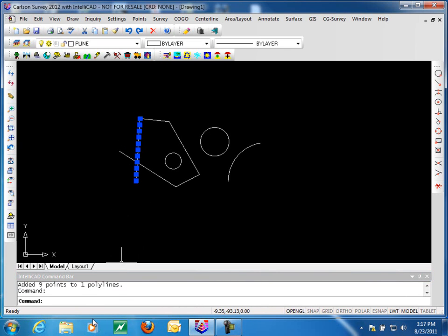What would this be useful for? Well, if I'm doing triangulation and I have a long distance, several hundred feet, with only endpoints, I'll get long, skinny triangles, which are not the best for creating contours. So if I can densify this, add some more points, I get more uniform triangles and better looking contours.